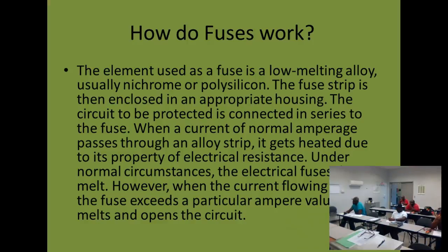Okay? Sometimes that's very simple. There's only one wire on this one, so if you pull one wire, you know it's not connected again. The only connection is through your meter. Sometimes though, there might be 4 wires over, 3 wires over here, so I don't know. Better disconnect them all. Okay. So for our meter here, we're going to cut the power for ohm, and we're going to isolate, okay?